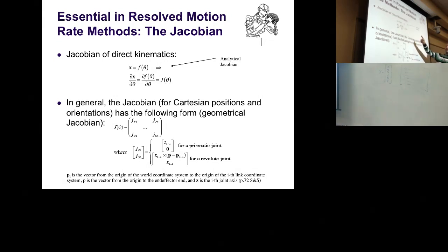Now, interesting, if you do the differentiation with respect to orientation, now you get into the trouble of did you use fixed angles, Euler angles, or whatsoever. You can do the differentiation. Remember, in the homogeneous transformation matrices, we have the big R, and we have the offset vector, let's call it O, and we have 0, 0, 0, 1. And here we have angles, joint angles in there, or orientation angles. These R's are based potentially on some Euler or fixed angle, and the offset vector is normal, not a big problem.